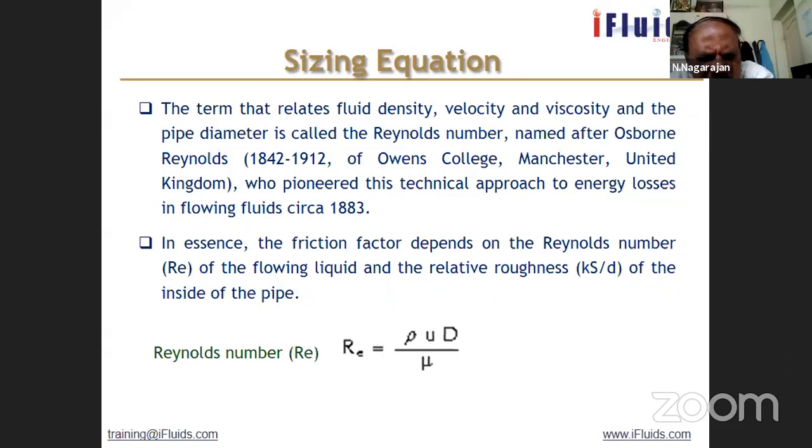So we put in a lot of margin. I said straight length, equivalent length, then we put some 20-30%. In the initial stages, we even put 30% margin. Suppose you calculate a straight length of 100 meters and an equivalent length of 200 meters, total 300 meters. We put a margin of 30%, which means multiplying by 1.3. So 390, almost 400. So initial estimates assume some margin like 30%.